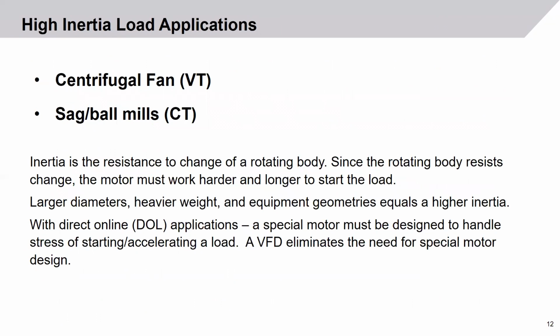High inertia load applications. There are some applications that have inertia problems. Such examples are centrifugal fans or SAG/ball mills. Now, the centrifugal fans are variable torque and the mills are constant torque, so the torque profile is not of concern here.